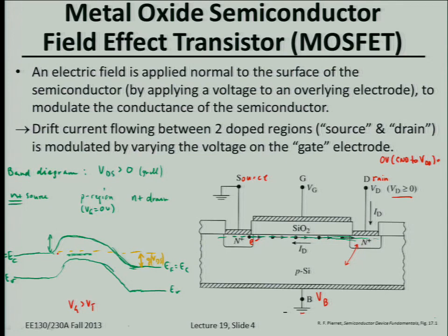To the 10^19 per cm³ of electrons. So when the transistor turns on, you have about 10^19 per cm³ electrons in the channel. Usually the source and drain regions, when they're degenerately doped, have a dopant concentration of about 10^20 per cm³. So you'll see a tiny little 60 millivolt or so hump here.